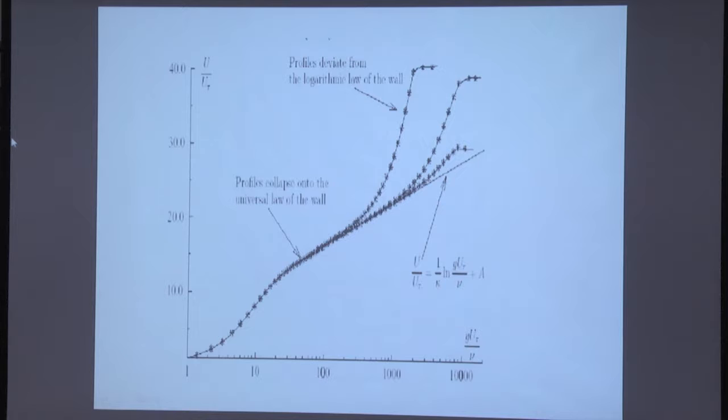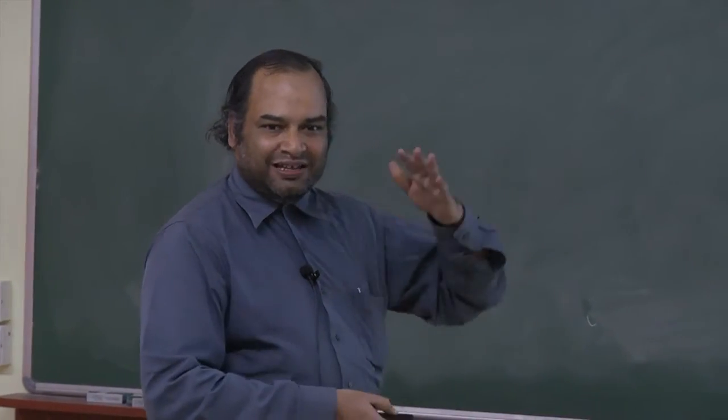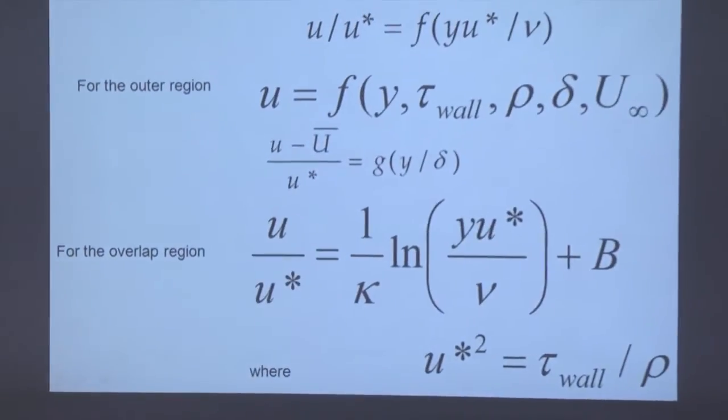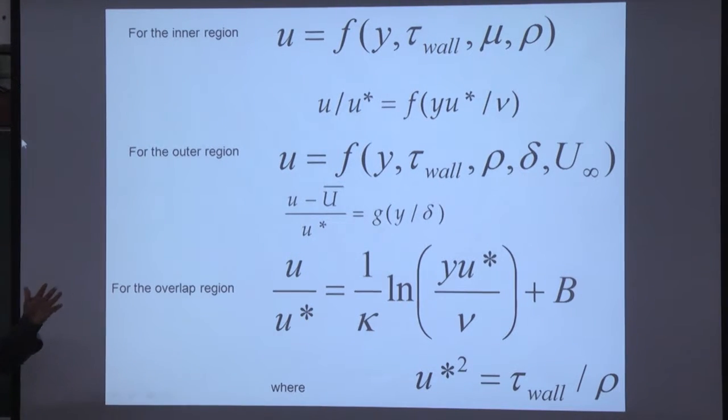This is of course one of those celebrated results in turbulent boundary layers, or pipe flows for that matter. In fact, there are not that many great, nice, neat results in turbulence literature. I would say this is one so celebrated that this Karman constant is thought to be, as I said, universal, which is not anymore. The other celebrated result in turbulence is what you heard about in the morning. Kolmogorov's celebrated result was the spectrum. And interestingly, I don't know if you realize that the Kolmogorov derivation also goes like what I said here. You divide this just as you divide it into the inner region and the outer region, and you expect there's a region where there is an overlap of these two behaviors. We'll see that later. Kolmogorov also goes about it this way.